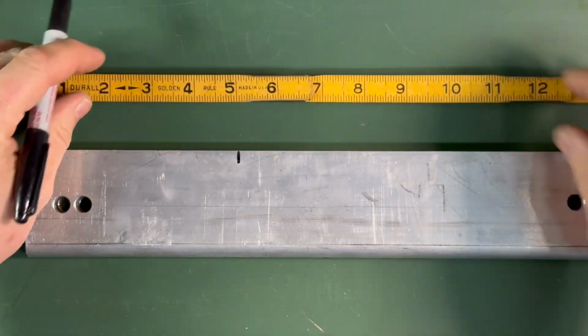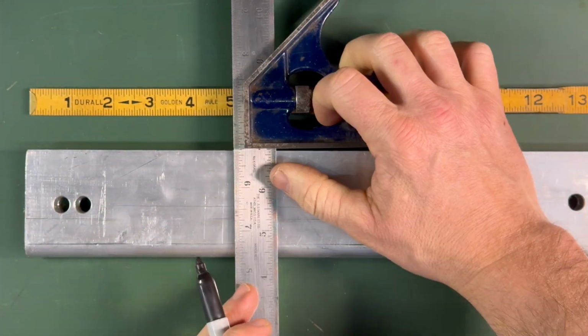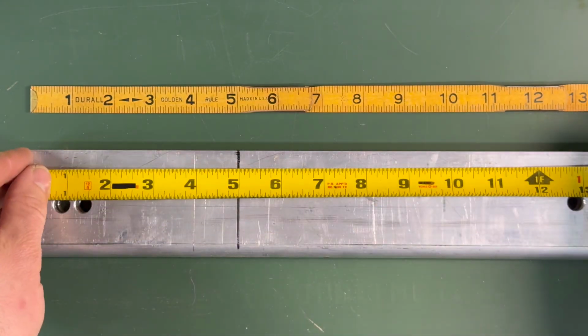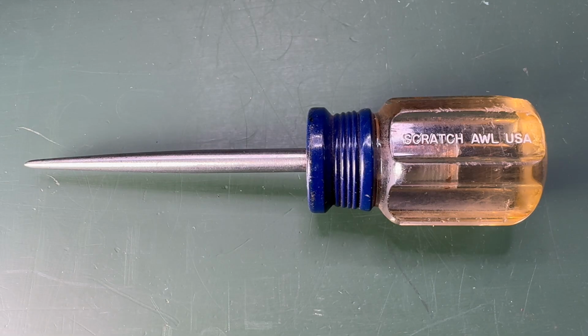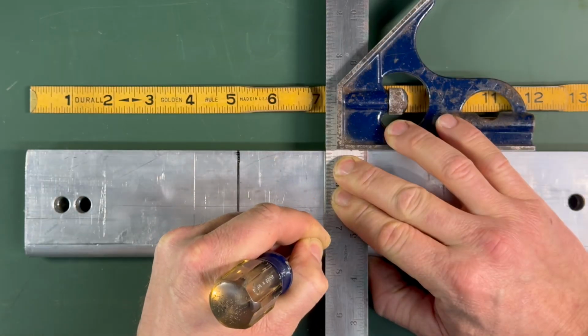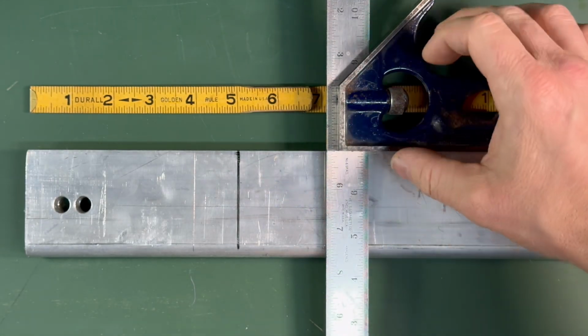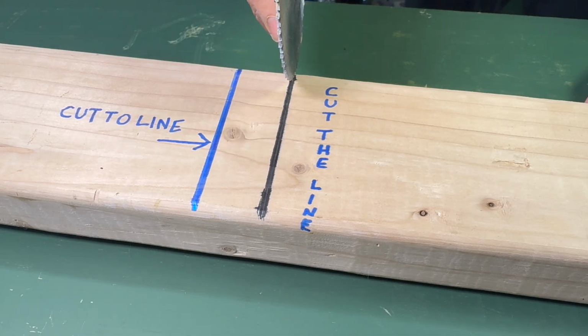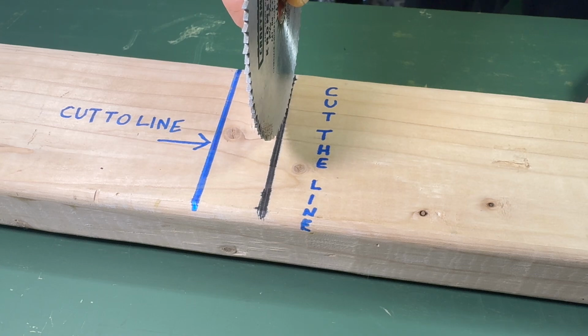Always keep in mind measurements are only as good as the person making them or the mark being made with them. Sometimes when marking a measurement, a pencil or marker line is okay. But when high levels of precision are needed, we must use a scribe or a scratch-awl that will leave a more precise mark. When making marks for cutting, we need to account for the thickness of the cutting blade or disc and plan the measurement for either cutting to the line or cutting the line, so the final piece ends up with the correct dimensions.